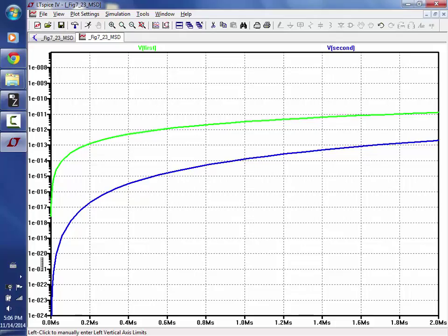Now, one thing you have to keep in mind is that when you do a DC sense, it's not actually DC. It's like windowing. It's a finite set of time where you apply a DC signal, look at it for a while, and then shut it off. I think it's the same for second order and first order noise shaping in my mind, but when I think of it that way, I have a pulse here. Wouldn't the second order noise shaping work better because it's actually a transient?